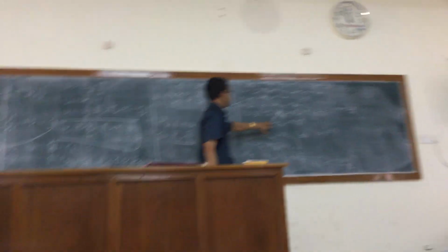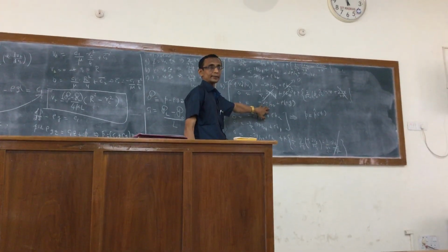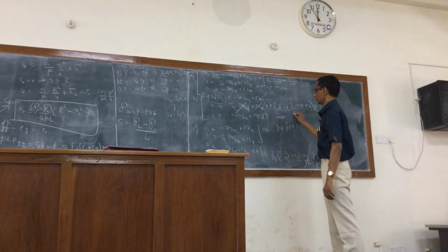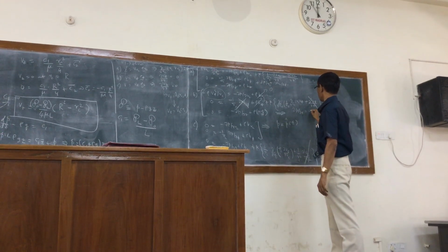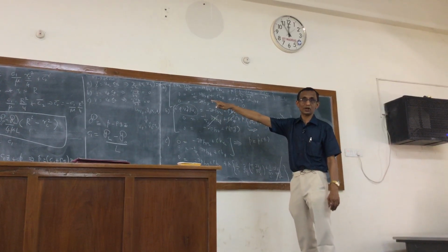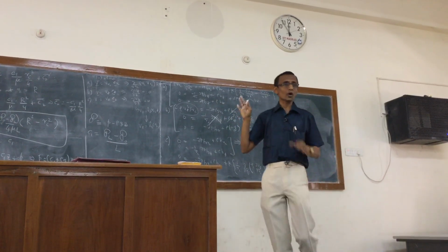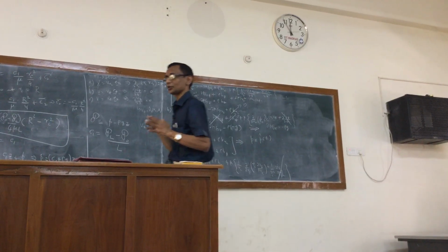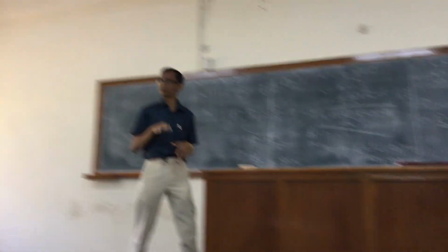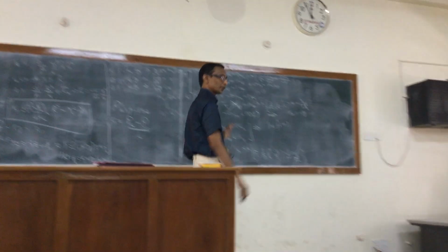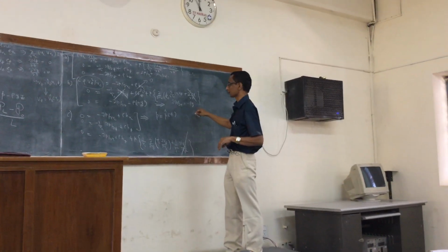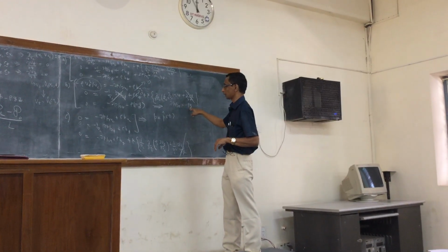Now let's look at the pressure variation. Pressure variation here, I can easily integrate this. When I integrate this, what I will get is dP by dz is equal to minus rho g. I cannot do anything about this yet because it depends on d phi. D phi is not yet found. So you might wonder, how are we to know what are the simplifying assumptions that you would have to make in a particular case. I will come to that question later. For now, I am just following the arguments made in Stewart, Lightfoot and neglecting certain terms. dP by dz equal to minus rho g.